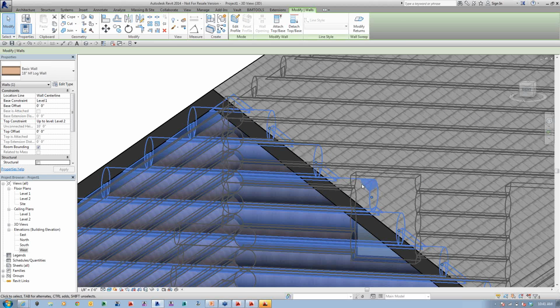The other thing to do is by breaking up the roof into separate roofs, meaning that I might have my metal roof on top with the sheathing so I can pull the metal roofing over and get a different effect. But then for my framing, that'll be a separate roof underneath so that my sheathing can go out over. I can do rafter tails with logs or something like that, as opposed to trying to do it with the insulation that's inside the house. So the roof becomes two parts in a sense.